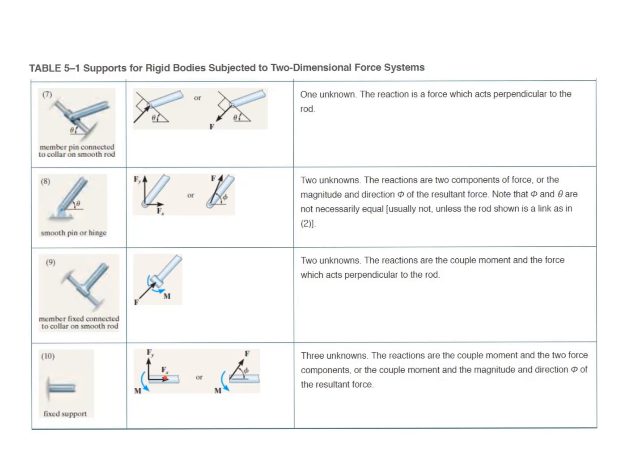And the same thing over here. You can take these two force components and represent that as a single force in terms of a magnitude and a direction, but you are still introducing two unknowns, not just one. And here we have two unknowns too for the forces. But the moment is still there in either case. A moment is sort of independent from the forces. You cannot combine a moment with a force like we could combine the two forces and represent that as a single force.